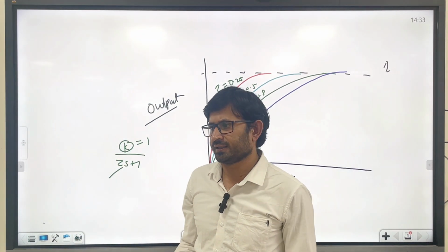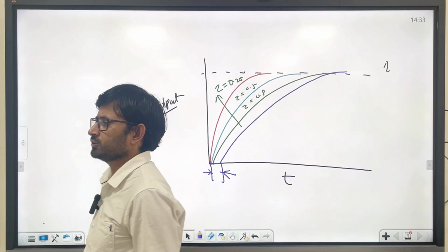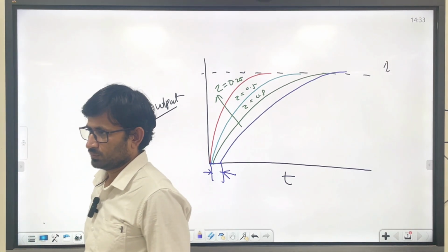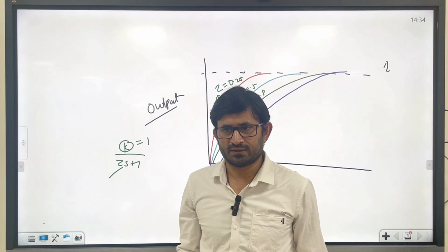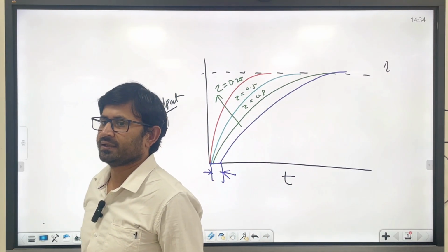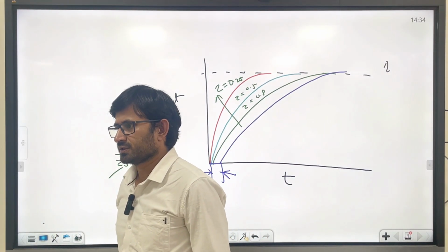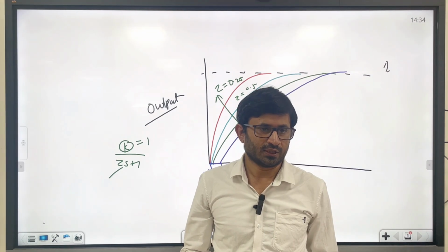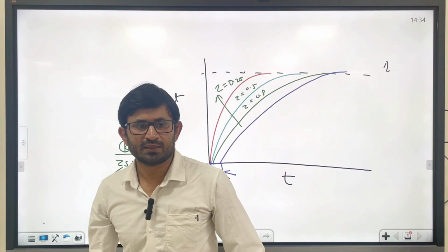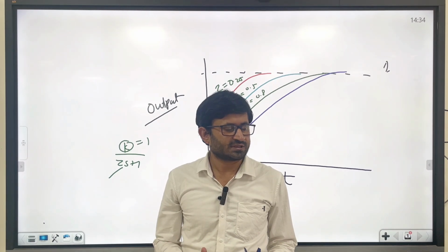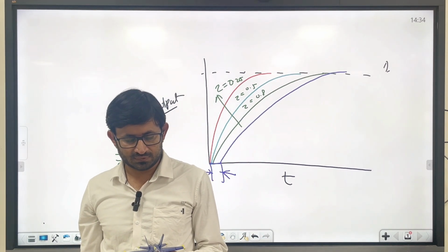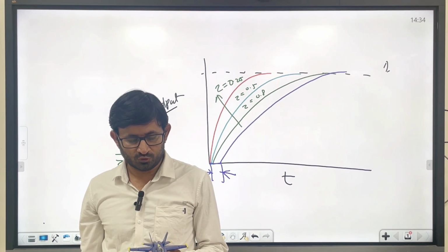If you sum up all the delay, then the question is what should be the value. So generally 40 millisecond, 80 millisecond is a standard delay which you have to consider in order to design the autopilot. And in a physical sense, you can have some feel for the delay.